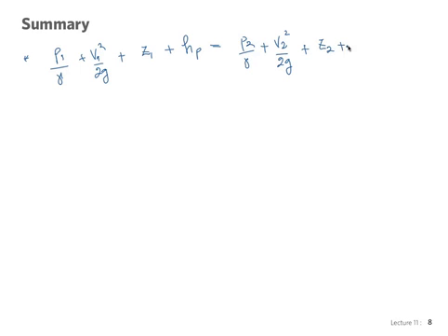So the energy equation we were happy with, and we checked all our signs and everything. In terms of fluid head, we wrote it as P1 over gamma plus V1 squared over 2g plus Z1 plus pump head is equal to P2 over gamma plus V2 squared over 2g. I'm not writing here the kinetic energy correction. That would only add little alphas next to the velocity, but I'm not writing it right now. Z2 plus turbine head plus head losses. So this was our full energy equation.